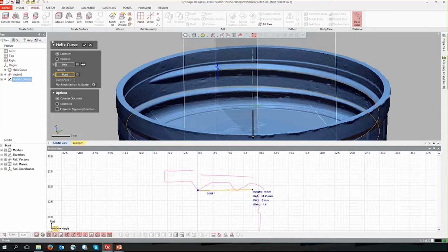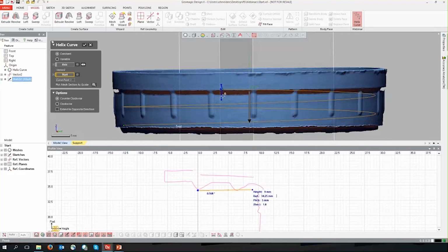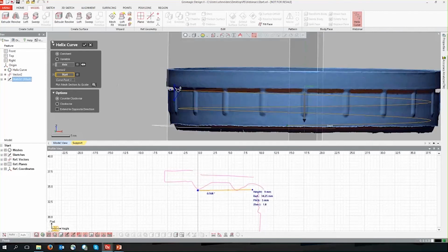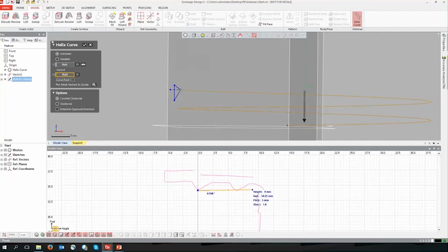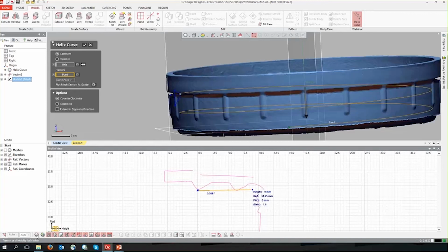Looking nice. So here we have some other parameters that we talked about in our setup tab. So we have our height, which is the top to bottom height of the helix. We have our radius, so this will be the radius at this point. We have the pitch, which is the top to bottom height of one time around, right? So if we look at it here sideways, we have the height of everything, which is the start to the bottom, right? So this other dot right here. Hide this guy, so top to bottom height, and then we have the height of one revolution, which is the pitch, which is the height from here to here. And then we have one more option here, which is the actual revolution.